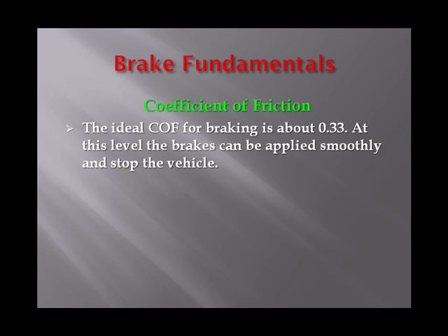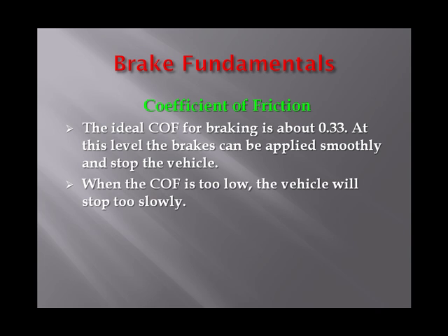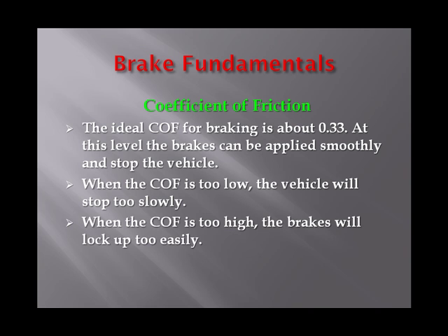The ideal coefficient of friction is about 0.33. At this level, the brakes can be applied smoothly and stop the vehicle. If the COF is too low, the vehicle will stop too slowly. When the COF is too high, the brakes will lock up too easily.